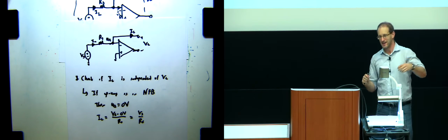There's two others that I think are more what I had in mind. Okay, so your question actually is very much related to what I was getting at. Notice I made this statement here, if the op-amp is in negative feedback. It is not at all the case that I can put anything I want here and still have the op-amp be in negative feedback.